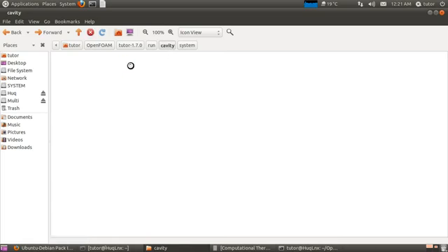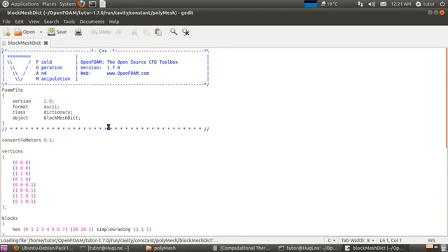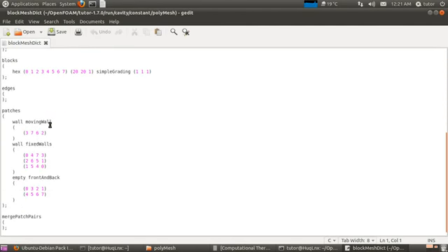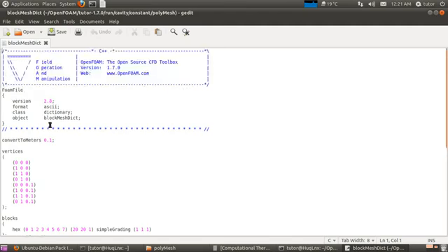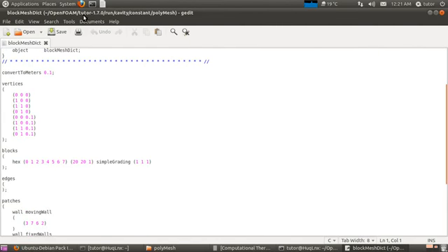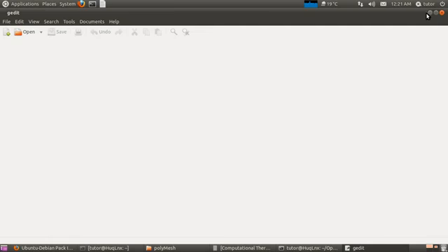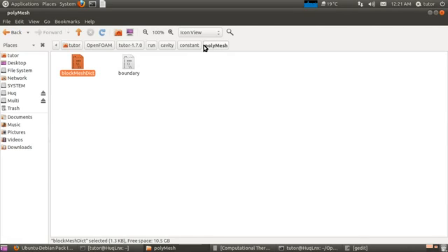And then back in the constant folder, polyMesh, this is the file blockMeshDict. blockMesh is the utility in OpenFOAM which is used for meshing, so it's the most common utility in OpenFOAM used for meshing. All the things defined in this blockMeshDict would be explained to you in the next tutorials, but just for the time being, just to show them that these are the important files. And then in 0 you have the files which explain the initial conditions of your system, so pressure and velocity.